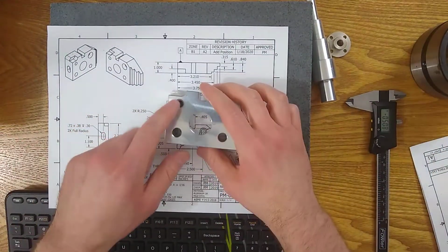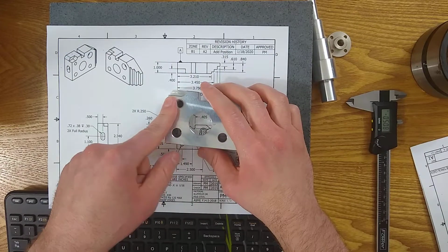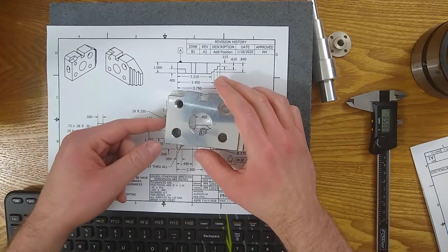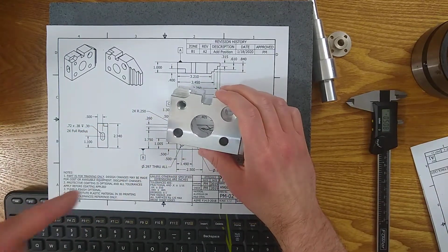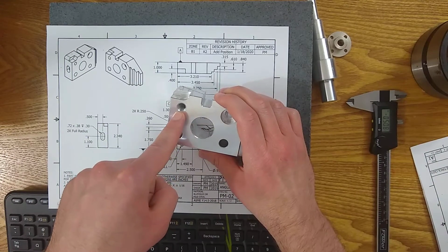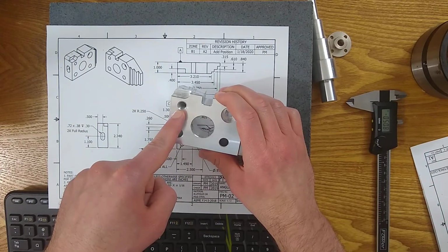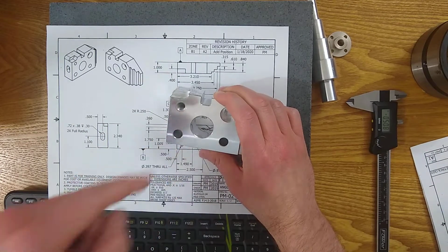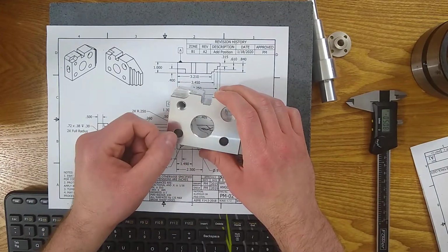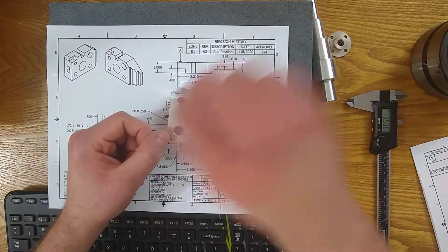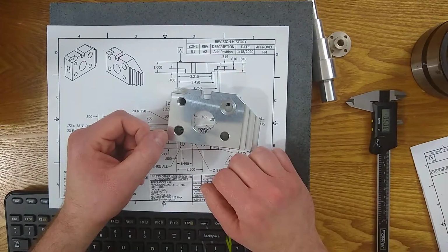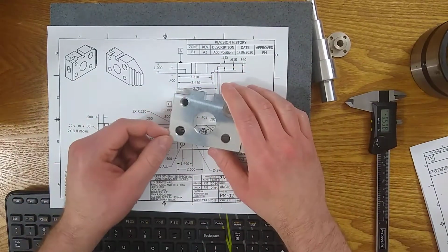And those use different through hole diameters. So it's possible to drill your through hole for a roll tap, okay, and then put the cut tap in. What's going to happen there is you're going to have a very loose thread because there's not enough engagement.